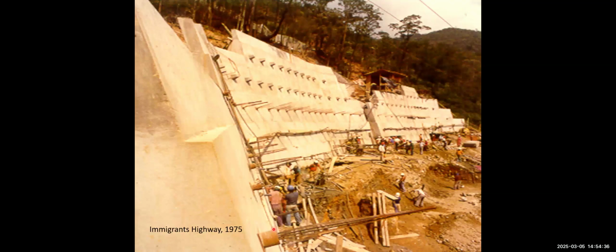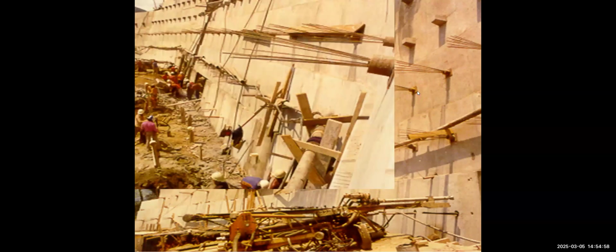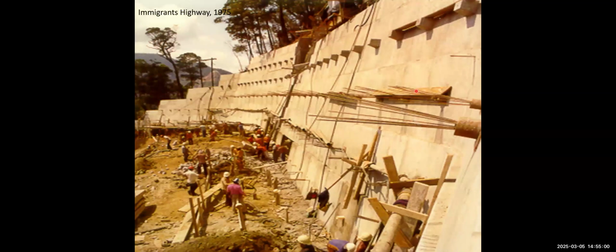This is a big wall being built in 1975, on Imigrantes highway that links São Paulo to the coast also. As you see, in those days, they used a lot of these multi-strand anchors without corrosion protection. And of course, we had lots of problems, especially close to the head where you have tension and flexion, okay?